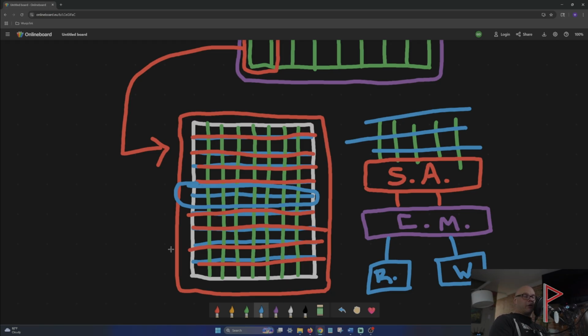If we can keep on going back to that row, the memory controller doesn't have to address the bank and bank group, doesn't have to address the row because it's already there. So it's only working with the 10-bit column address. If you can keep on hitting that row, that's called a row hit. The more often you can go back to that row, the more efficient and quickly your DRAM is operating.